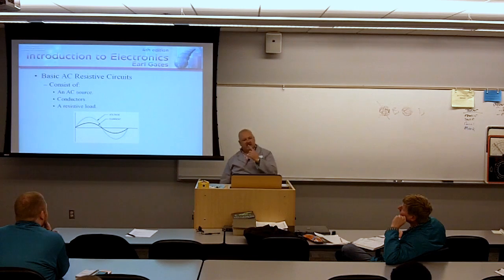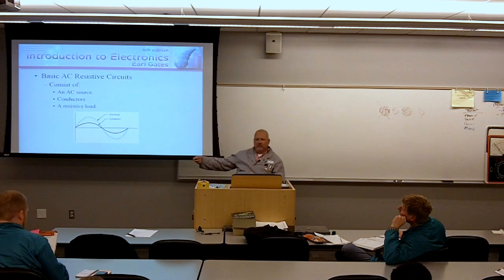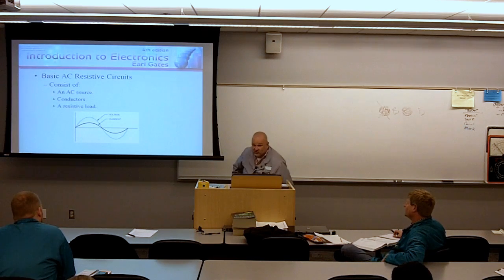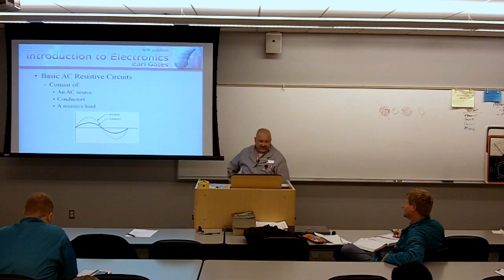No. Can I see the effective current on the oscilloscope? Yes. So if you think you're going to call the oscilloscope up and say, well, look, this is current and this is voltage, you can't. All the oscilloscope will display for us is voltage over time. So we can't see this display on the oscilloscope. But we can look at this as an XY plot to show the relationship that voltage and current have.